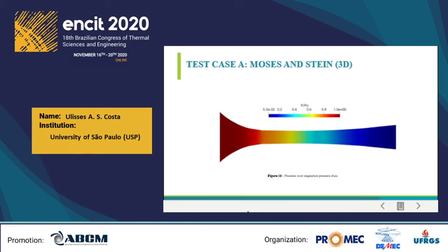It's already been pointed out that the occurrence of condensation leads to an increase in the flow static pressure. This is illustrated in Figure 10, which shows a pressure slice. The flow static pressure is decreasing continuously until there is an increase in static pressure due to the occurrence of condensation.